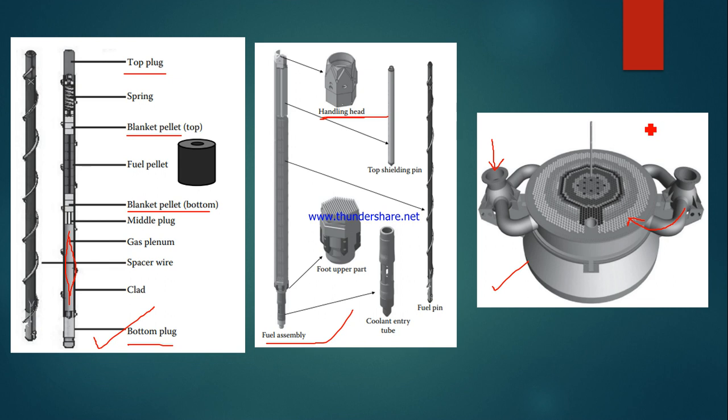The heat will be extracted because the secondary sodium will be on the tube side of the primary heat exchanger. Then it will go to another heat exchanger, the steam generator, where the water Rankine cycle will generate the pressure, which will be expanded in the turbine, and it will rotate. So this is the typical fuel configuration in a fast reactor.